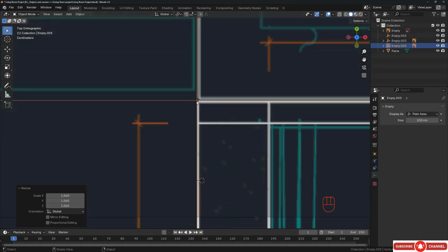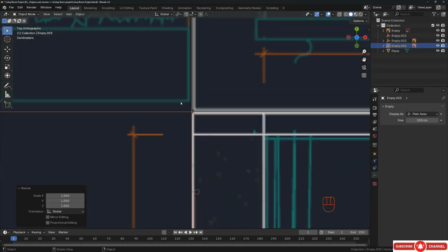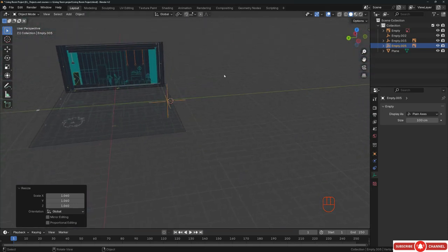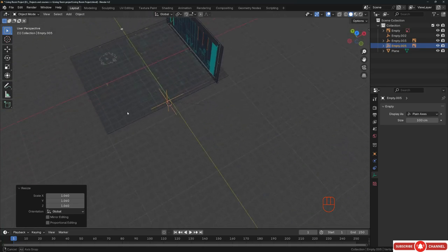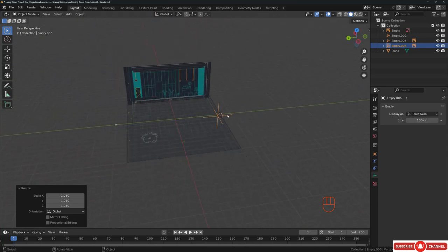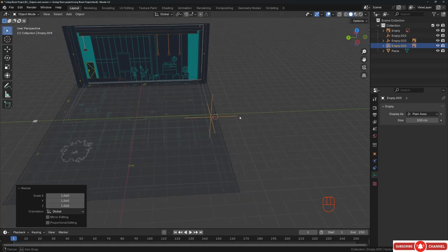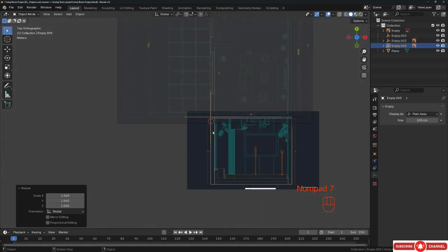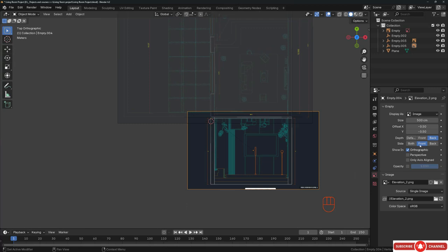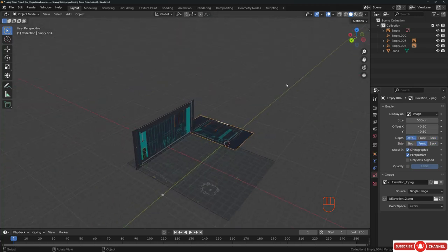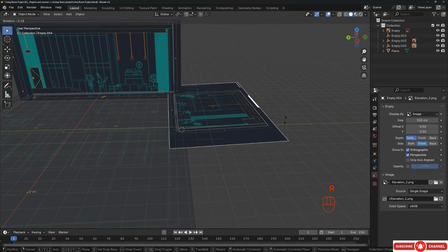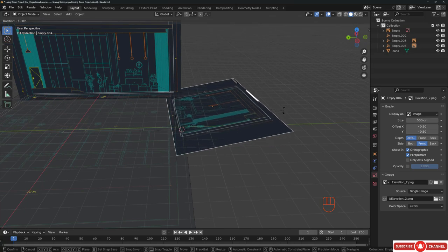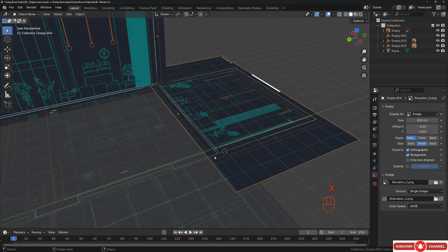Alright, perfect. I guess we can, yeah, that's very cool. That's all what we want to do here. After that you can rotate it, but when we switch to the perspective it's disappeared because of the settings right here. So I will change this to perspective to be visible in the perspective as well, and I will change the depth to defaults, and now I will hit R to the X this time, but don't select the image, select the empty instead.